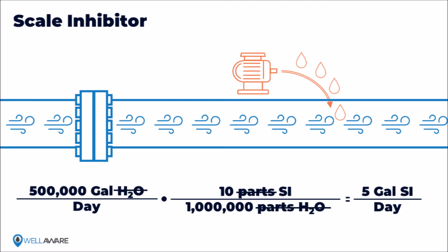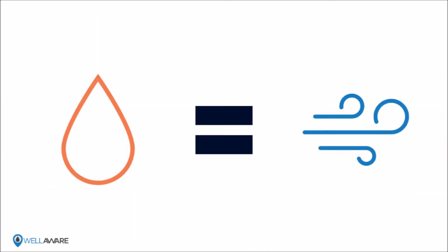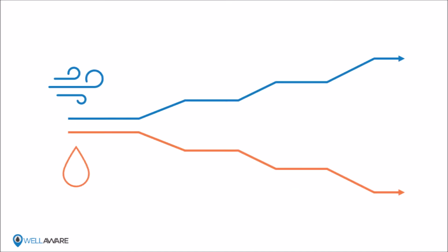Based on operational parameters, sometimes chemical injections don't actually hit this target. This is what we call variance, the difference between the target injection rate and the actual injection rate. To avoid variance, we want to change our pump set points to match our target rates whenever those targets change. This is where things get challenging.